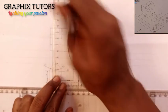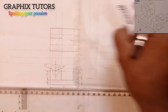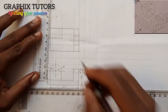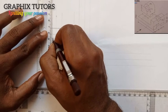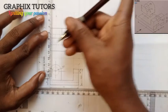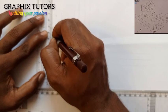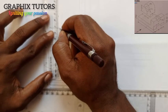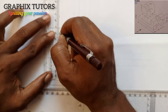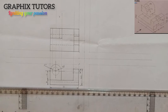Now I'll use my hidden line to show that there's a circle going through. I'll use a long one, this, then I'll come here and do the same thing. That is what we have there. The hidden line is showing that there's a hole going through there, right?